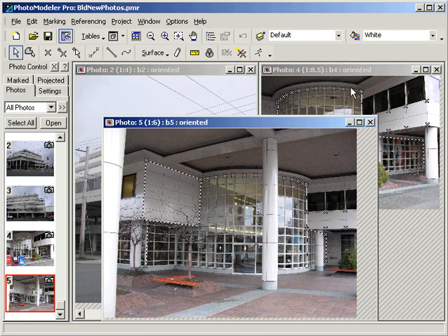These points along the top of the glass window in the lobby have been marked and referenced across these 2 photos. We want to create a curve which will be used to create a curved surface using a surface feature called Sweep. We will create the curve using the Curve from Points feature. We zoom in on photo 5 for a closer look.